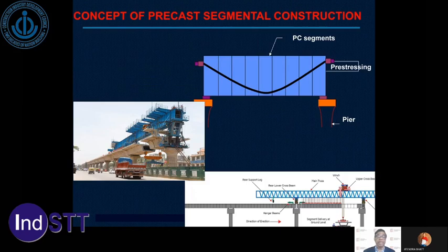In this process, we need to realize that design and construction method have to be kept hand in hand if one wants to realize a good efficiency. For example, for the metro projects, superstructure being done in many cities today, the precast segmental construction method is very appropriate in that it has the least disturbance to the traffic which is flowing all the time in crowded urban cities. So here again, we are sure that the construction method and the design method are very closely interlinked and have to be taken together.